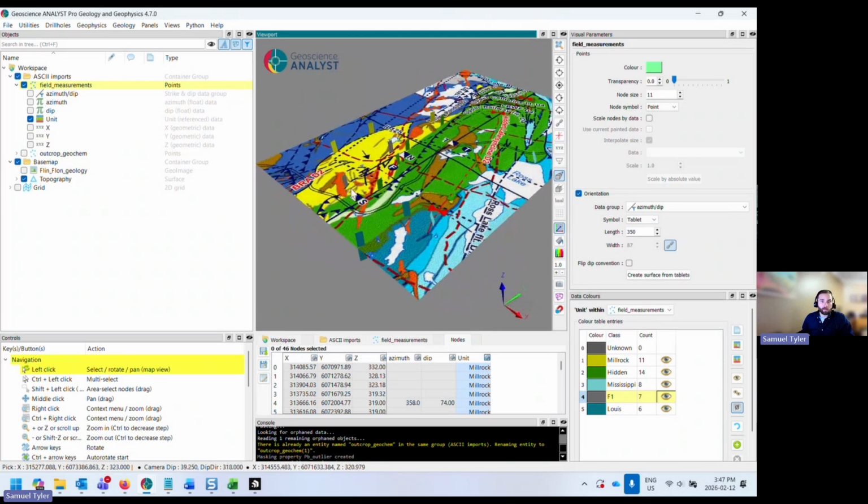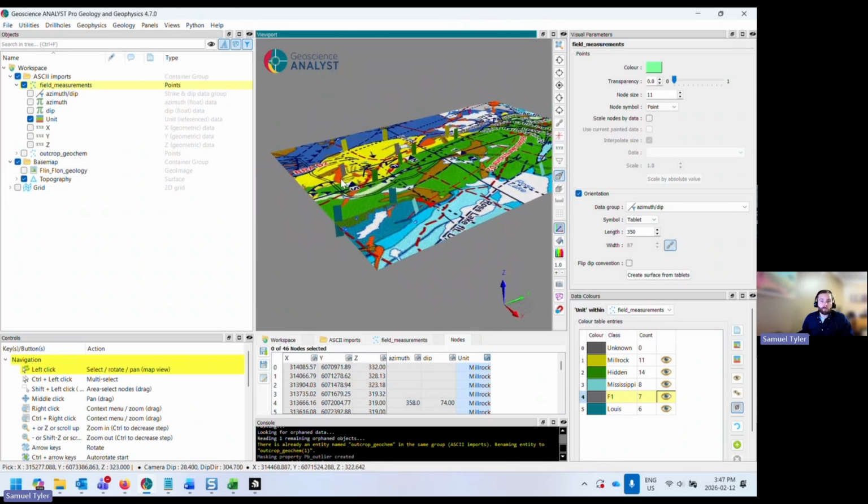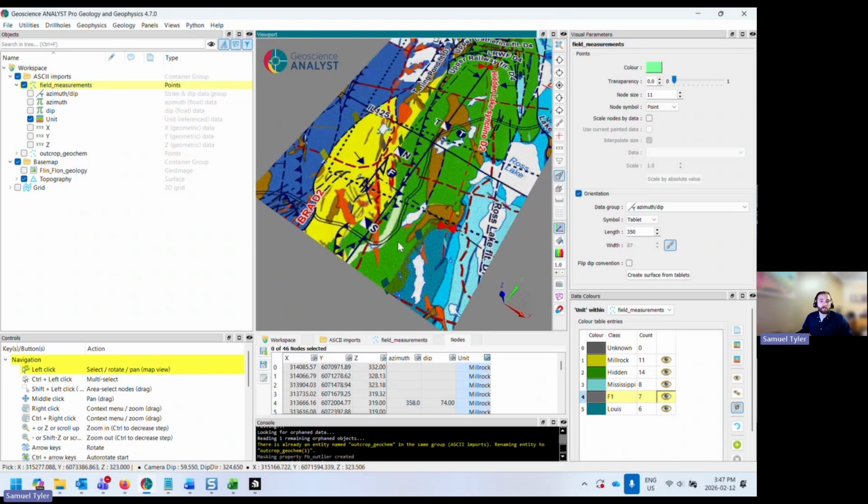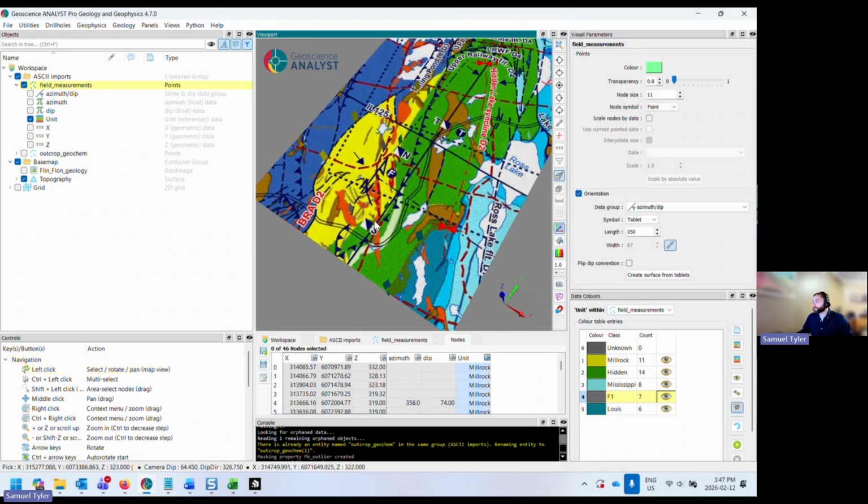Basically, the idea here is that, starting from before we have drilling, to come up with a drill target, we need something to point the drill at. And usually the first thing we can put together is a surface projection based on our mapping or based on structural measurements. So if we're lucky, we might have a geophysical model and we can target a geophysical region. But for the sake of this one, we'll just build a surface, and then we'll build a set of surfaces and then bring in some drill holes to test those surfaces.